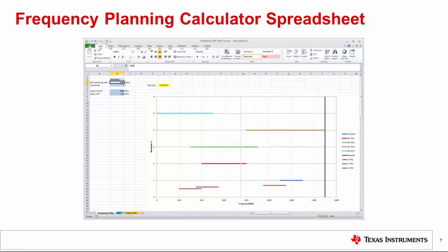Once these parameters are entered, a visual representation of the first Nyquist zone is shown. The x-axis shows frequency, while the y-axis shows the fundamental, interleaving tones, and second to fifth harmonics. The most prominent overlap tone is identified in the overlap field. Once the initial overlaps are understood, the user can update the ADC sample rate or input signal parameters to determine the best combination to eliminate or minimize overlap.